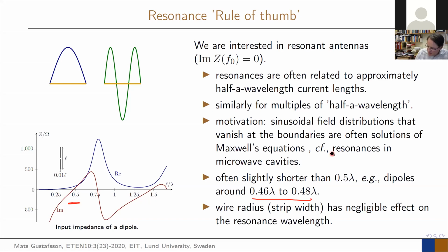And in these cases, it can also be shown that the radius of this actually has a very small effect on the resonance. There is a tiny effect on it, but it's not a big effect. If you start to make it very fat, so you make it 0.1 L here, it will shift. But if I go to a width that is 0.02, 0.001, it doesn't change where this resonance is. It will change slightly the bandwidth of this one, and I'll come back to it.